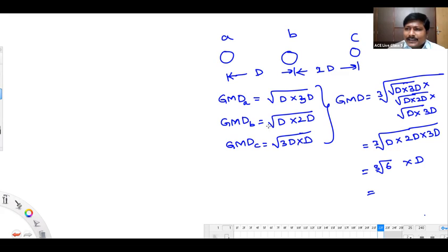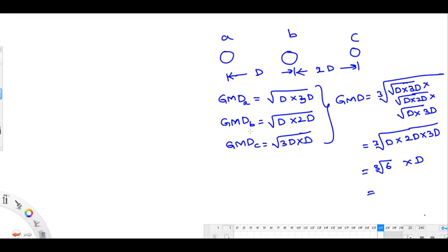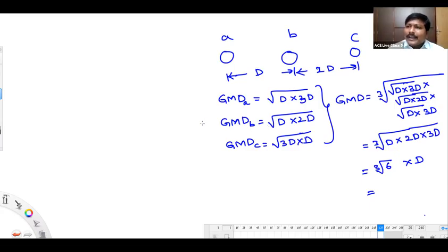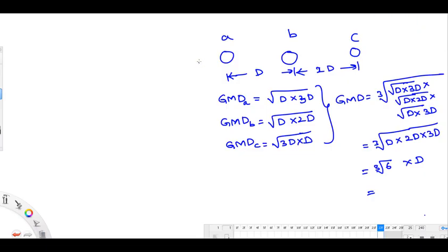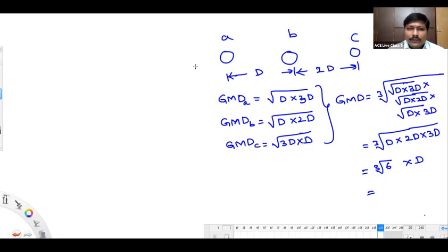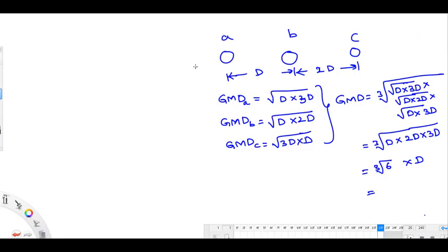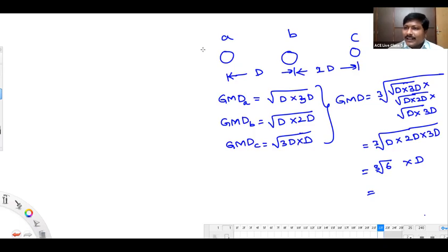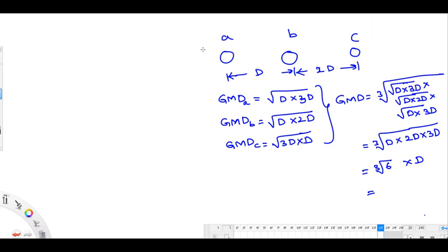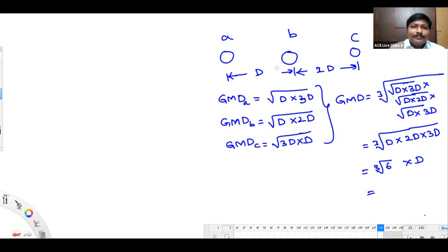See, while you are doing a transient study, you need to trace the voltage value at each and every point on the line, whether there is a rise or fall in the voltage. So we have to track the voltage at all places along the line. For that purpose, you have to go with the distributed model only. And for any type of length, we use the long line model, sir? Means any type of line. For any line, if you want to do transient analysis, obviously you have to trace the voltage at all places, right? Okay, sir. That's it. Any other doubt here, Bhaskar? No, sir.